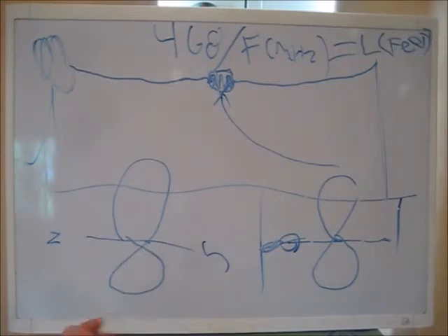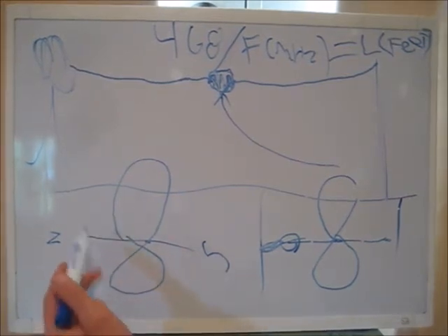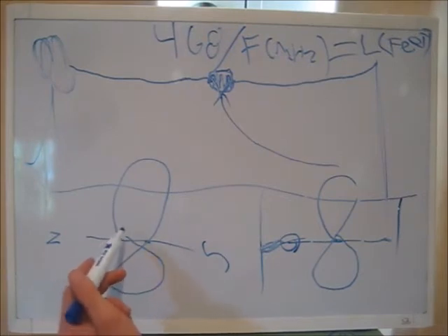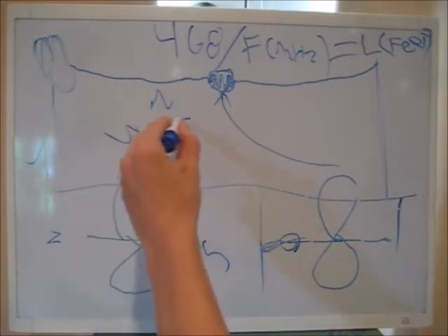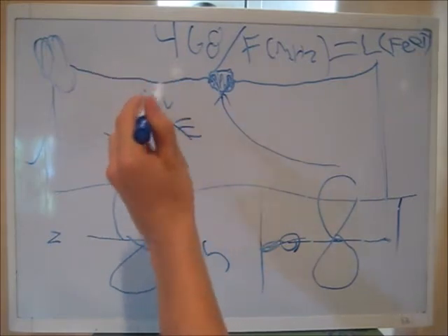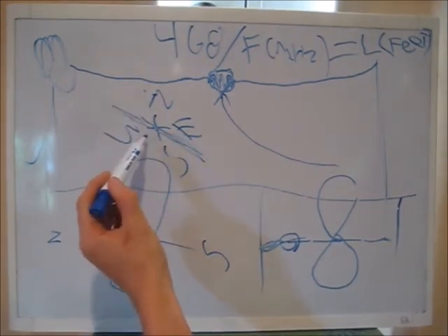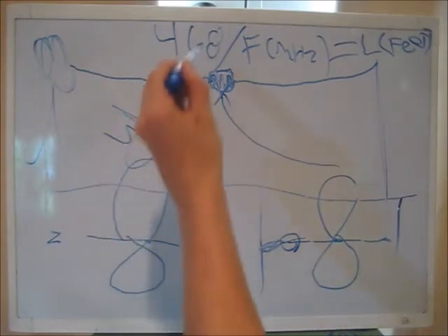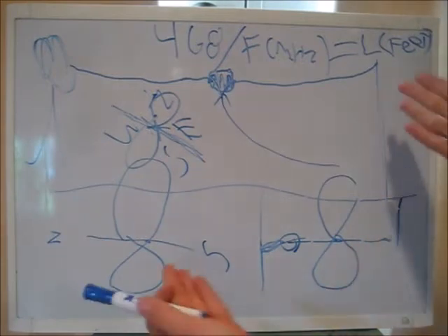So if you plan to talk to Europe a lot, you probably want to point your antenna northeast. For most of the United States, northeast is a good way to point your antenna, which means that this is going to face sort of northwest. So north, sorry, I blanked out here, north, south, east and west. Very terrible compass here, but you'd want to put your antenna running like this, because figure 8 broadside is going to point it northeast up towards Europe. So that's a basic concept of dipoles, and that is a very messy dry erase board.